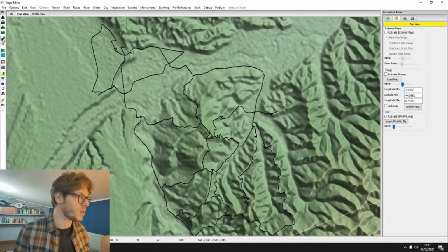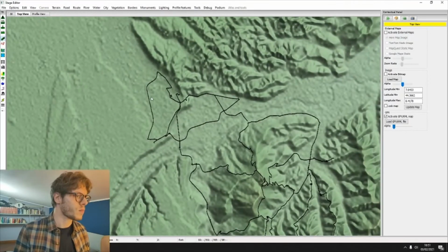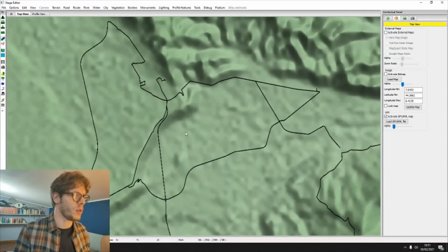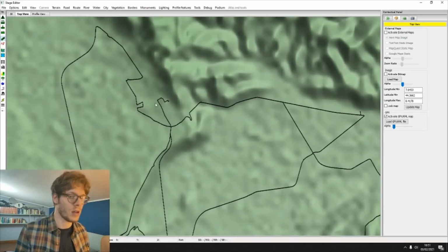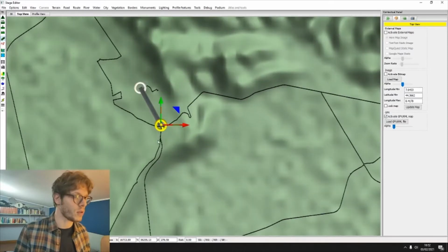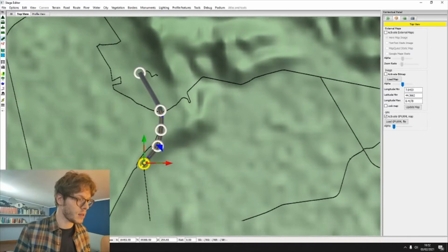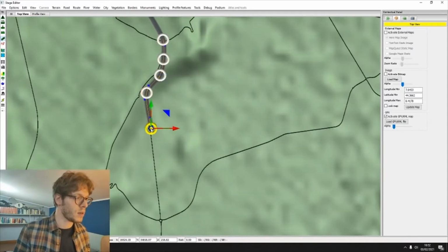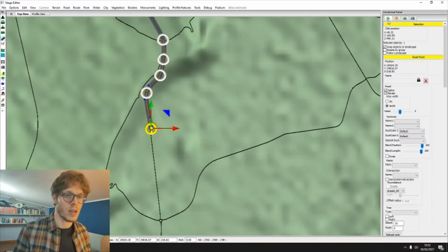You see that there is a small button. I hope that you see the mouse. Yes, it's activated. Here we zoom, we select a point that was almost here, and with the right button of the mouse we click here and we start to track all the points of the road. So tack, tack, tack. We've got here in this section all the visualization about the information of the road that we are tracking.